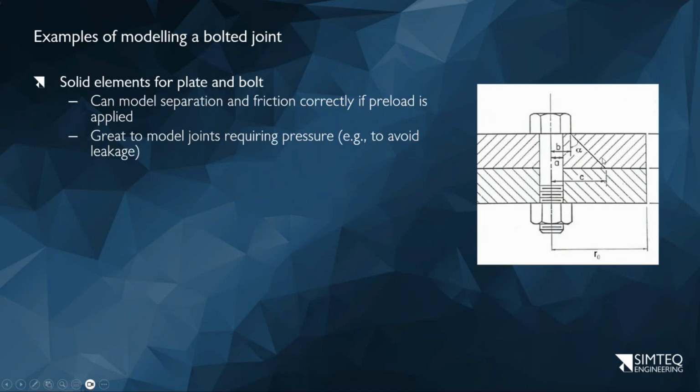The purpose of the bolt is keeping these plates together and they slide on that face effectively. So even if you hand tighten it, what will happen is due to that load, it will slide and will press there on the one side of the bolt and there on the other side of the bolt. So it's a very short section that's actually in shear. The rest has a very small amount of shear, at least in the bolt.